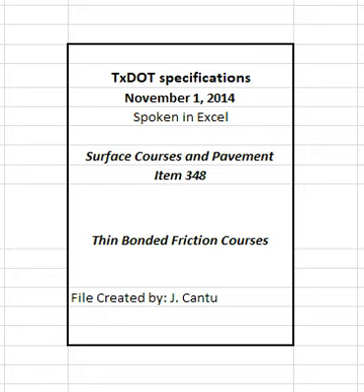for bituminous mixtures. Fibers may be pre-blended into the binder at the asphalt supply terminal unless otherwise shown on the plans. The contractor may reduce the amount of fibers when at least 3% RAS is used in the mixture, as specified in Table 8, Note 3.